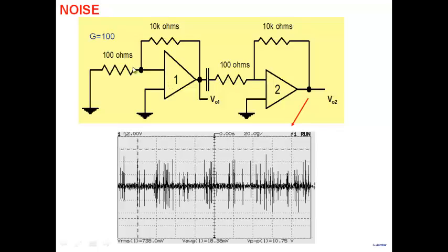So my op-amp here, this is an amplifier. The op-amp is generating noise. The resistors are generating noise. Similarly, this op-amp, this resistor, they all generate noise. All the noise is getting combined, and we are looking at the total amount of noise at the output. This is true of all amplifiers. You don't feed in anything at the input, and at the output, you will always find a certain amount of noise that is present.